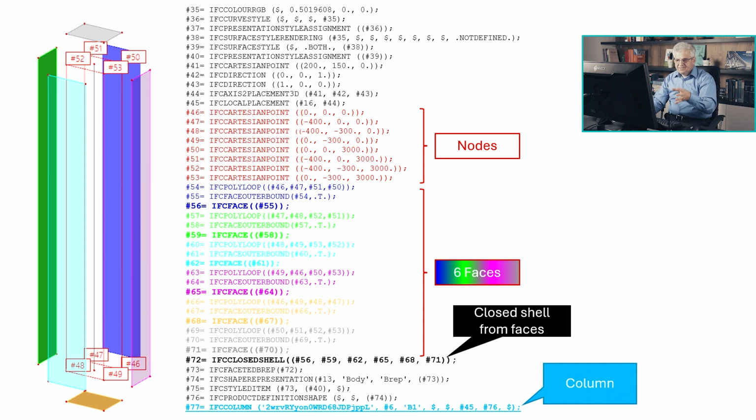And on the left side, you see the boundary representation. This is like a shoebox. So you get only these faces and there is nothing else. The axis is there because this is a drawing from SCIAEngineer, but you get only these colored faces, and this is then imported. Sometimes they are also open, so there are gaps between the lines. Then you get open shells, and you cannot convert them into 3D because SCIAEngineer cannot imagine what is in these gaps. So this is sometimes difficult.